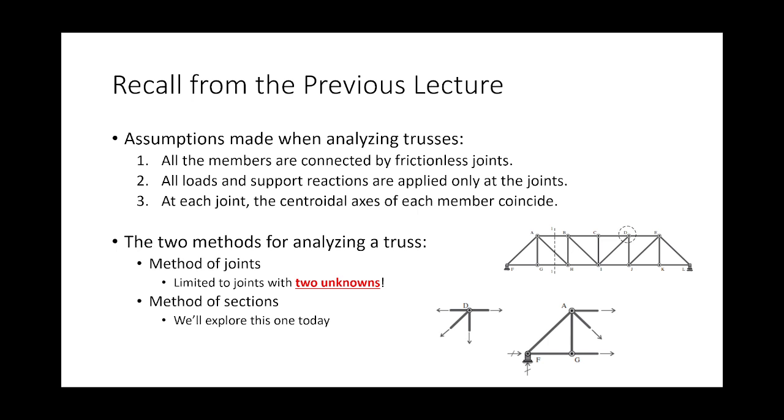So we have a particle statics problem, so the forces are along the axes of each member. Really the kicker is, what's the magnitude? So remember, how do we define forces? Magnitude and direction. So all we really care about is the magnitude of the force inside each member, and the direction being whether or not it's tension or compression.